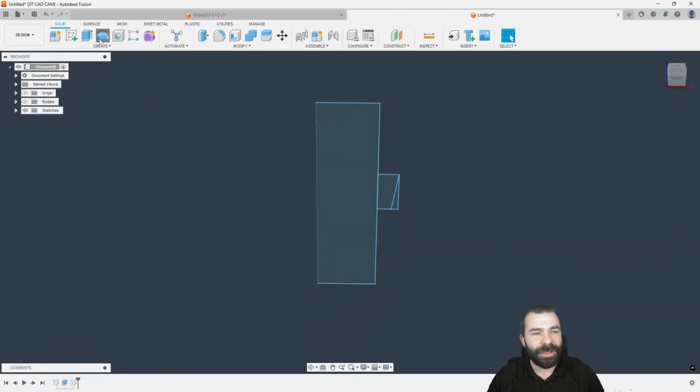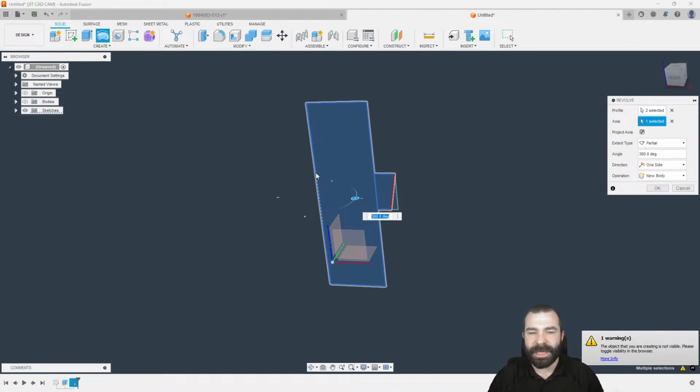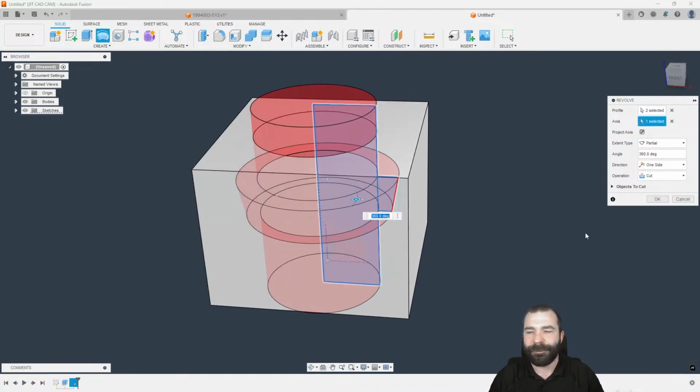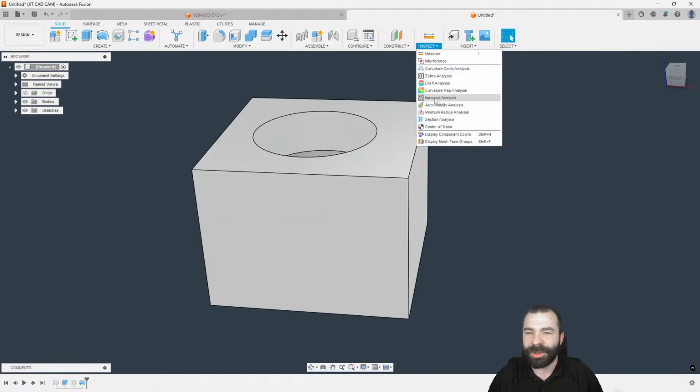Again, you guys could dimension this a lot more, but as you're going to see, we're going to go ahead and pick our boundaries. We're going to go ahead and set our center of rotation, which has automatically been picked up on there. As well, there is our body for the revolve move. Again, we could go in. I just Control Z'd some stuff.